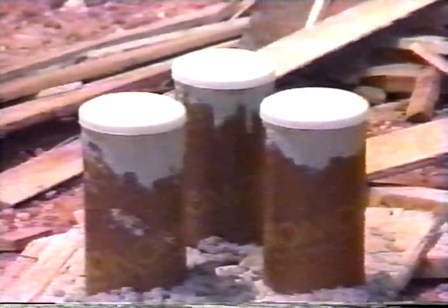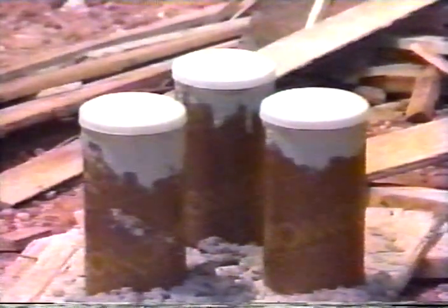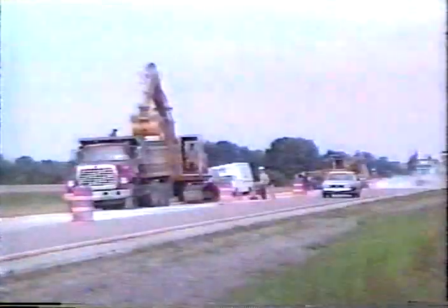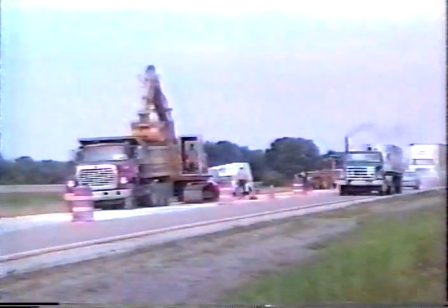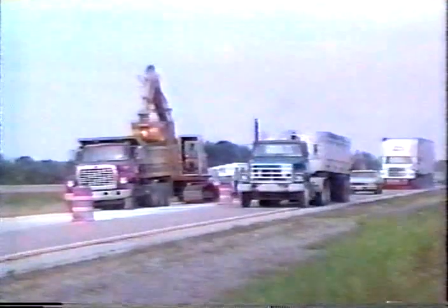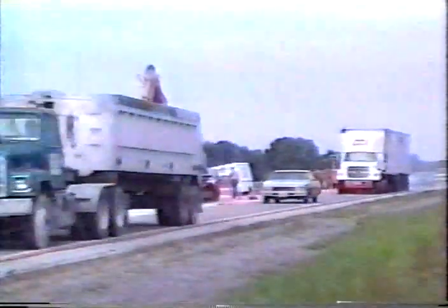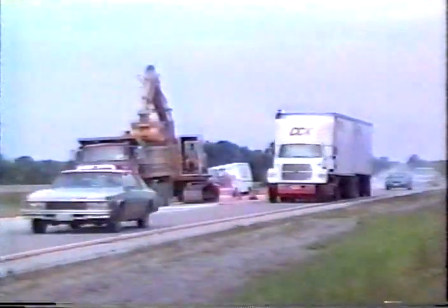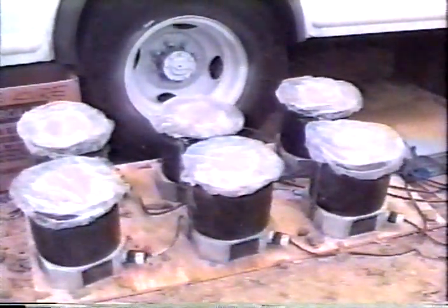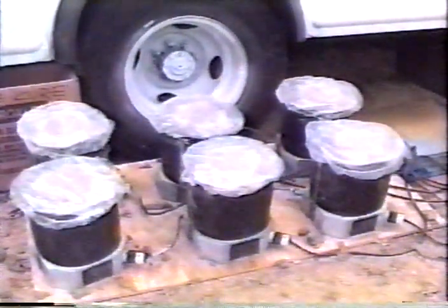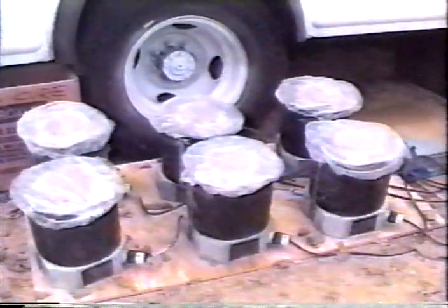Field-cured cylinders fail in many cases to reflect the actual strength of in-place concrete, especially in the early ages. Better prediction of the actual in-place strength has been needed, especially when traffic opening times for highway repair work must be determined. One effective prediction technique is the temperature-matched curing system, or TMC.